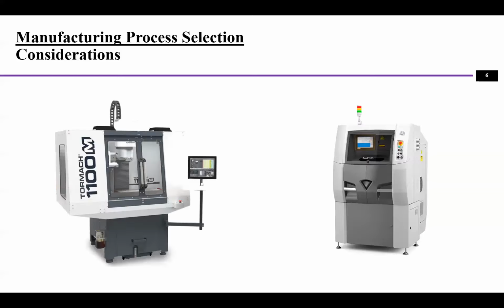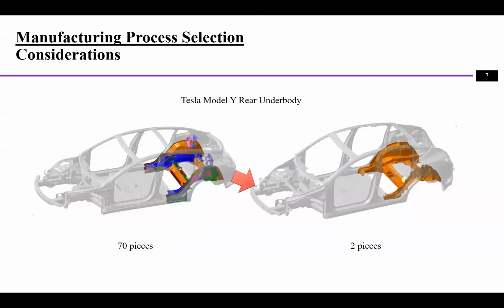Well, say if we want to do the machining, on the left, this is the CNC machining center, while on the right, this is a 3D printing center. As you can tell, the cost for the CNC center is only $20,000, but the metal 3D printing center is actually $500,000, and that is a basic level for metal 3D printing. So when you are choosing the process equipment, the cost of the process is another big factor you have to consider.